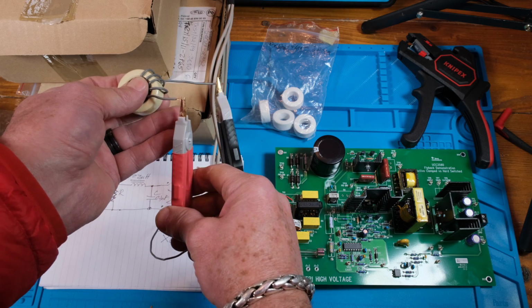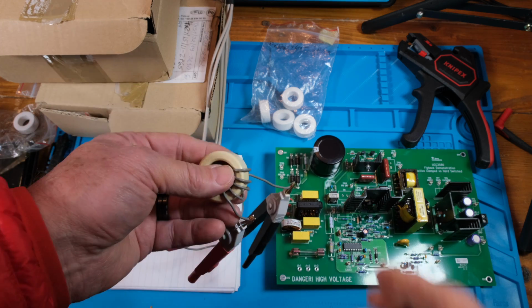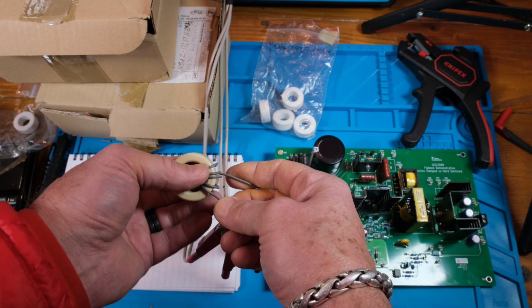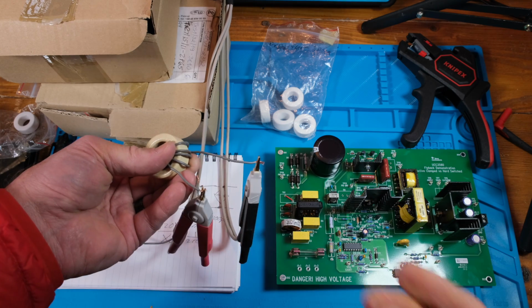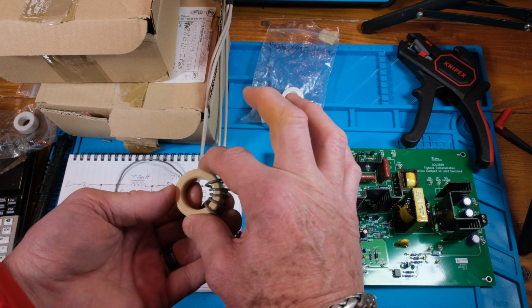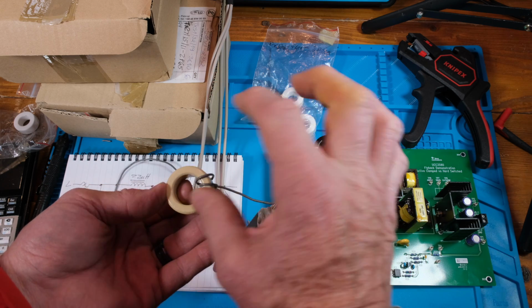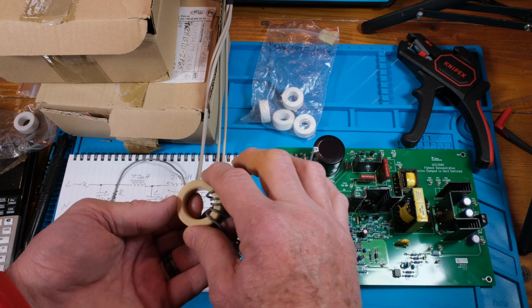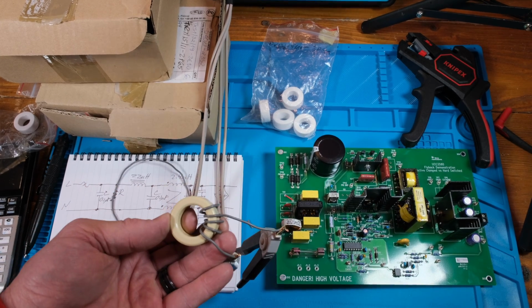Now the size of the core isn't really why I'll get more inductance. Yeah, now I'm at 513 microhenries, so that's great. That's what I want, higher inductance. It's the permeability of the cores, the type of material, and then the size will help you carry more current without it saturating. But let's go ahead and wind the other wire.